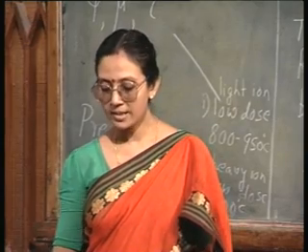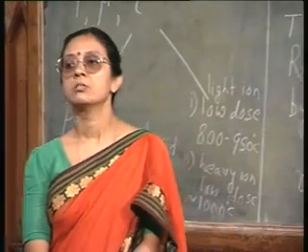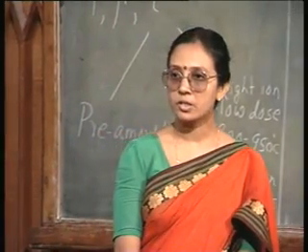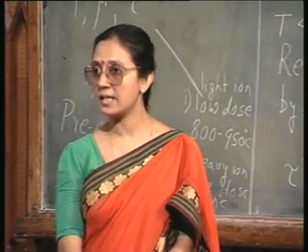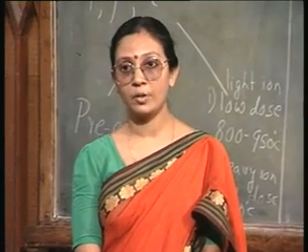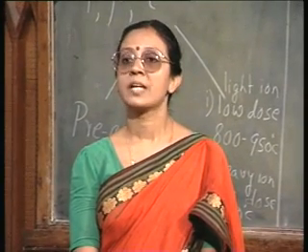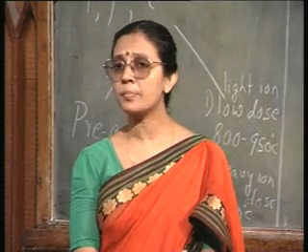Now, let us consider a few practical cases. We will take the case of phosphorus in silicon, boron in silicon, and arsenic in silicon, and see how exactly upon annealing the carrier activation recovery takes place, because that is the prime concern.